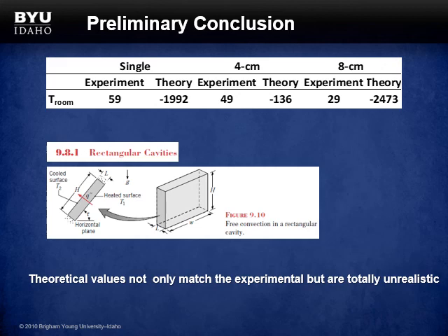Our calculations were done using the resistance method, and it seems that our area is so small that it is giving us very high values for the convection resistance. If we just consider conduction resistance, we achieve exactly the same temperature that we got from the experiment.